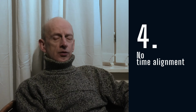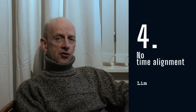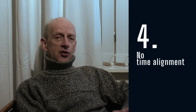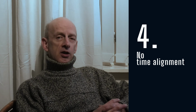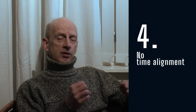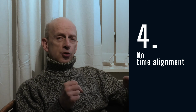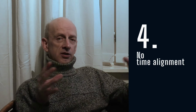We need the whole frequency range to see the complete picture of the sound. Number 4, no time alignment between subwoofers and main speakers. This is common when main speakers are run directly with no filter, no processing. There may be an analog filter on the main speakers, but if you don't have a digital processor on the main speakers, there is no possibility to add the proper delay on the main speakers, and then it is impossible to get proper time alignment.